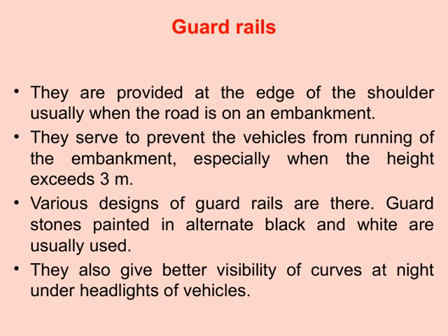Let's talk about guardrails. These are typically installed at the edge of the shoulder, especially when the road is situated on an embankment. Their main purpose is to prevent vehicles from accidentally running off the edge, which is particularly critical when the height of the embankment exceeds 3 meters. You might notice that there are various designs of guardrails, but a common feature is the use of guard stones painted in alternating black and white.